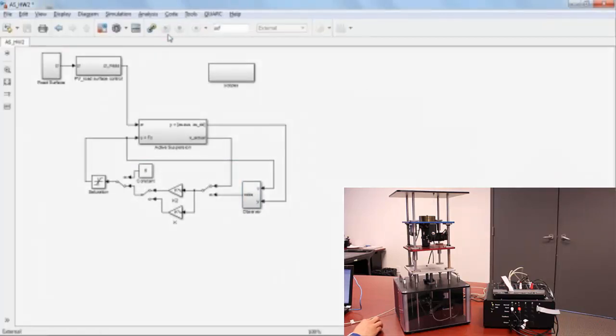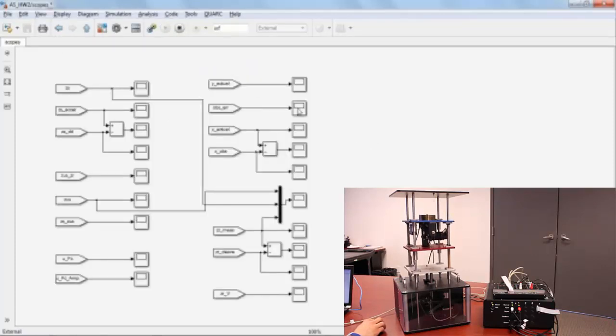So now I connect to our target again, let it run, and you can see it move, and you see something that you would expect. So you see that our controller is working, that it is stabilizing our car model up here, but there is some slightly higher oscillation going on than we had before, where we actually used our filtered states.